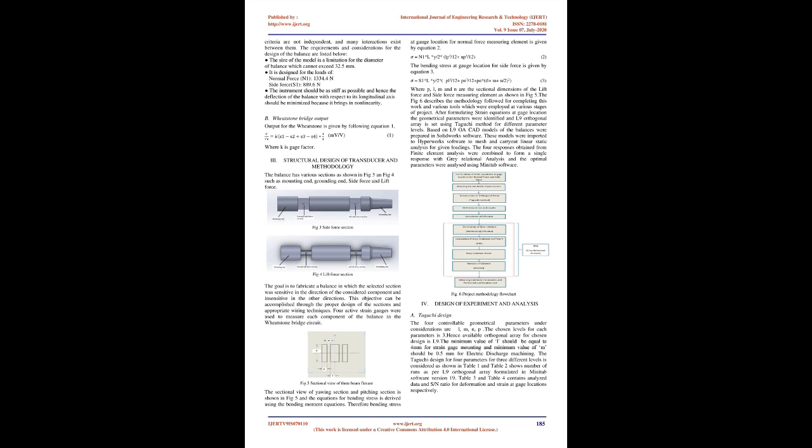4. Geometrical optimization of strain gauge force transducer was carried out. Multi-objective optimization for maximizing stress capacity and reduce volume. Combined Taguchi-based GRA was used to optimize responses obtained from finite element analysis. 5. The balance designed by earlier researchers 1 to 4. There is no mention of using 3 rectangular beams for measuring normal force and side force simultaneously. In this regard, an existing cross-beam flexure was replaced with 3 rectangular flexure, and optimization carried for improved rigidity and sensitivity through Taguchi-based Grey relational analysis.